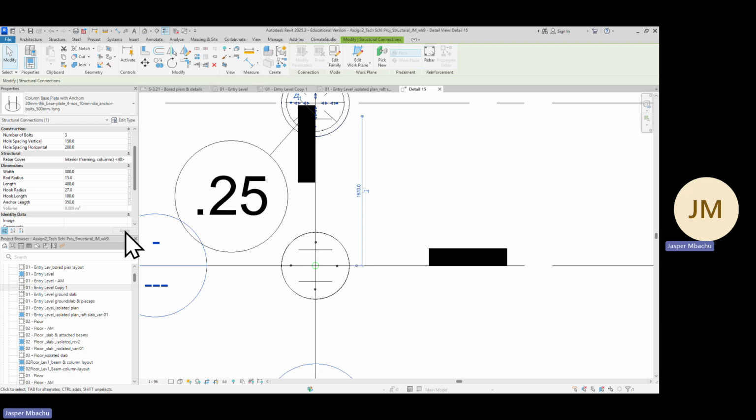Also removing some. We just want only the grid lines that cross through our columns. And any other grid line, any other section line that doesn't do that, you just make it cleaner. Yeah. There are too many here, it's too noisy.